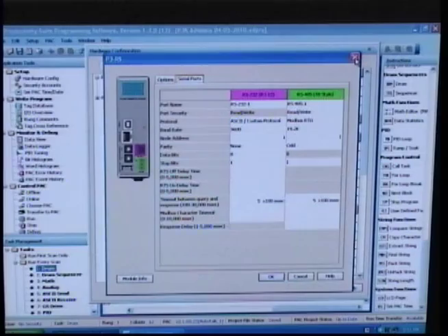We also should mention, we mentioned in the past that I can have my CPU over here on the one side and, through an Ethernet cable, have a remote slave sitting out there with an RS module, and on the front of that is a USB connection. I can actually walk out to another location in my factory or plant and plug in my laptop and sit there and program and monitor and make changes to the program.